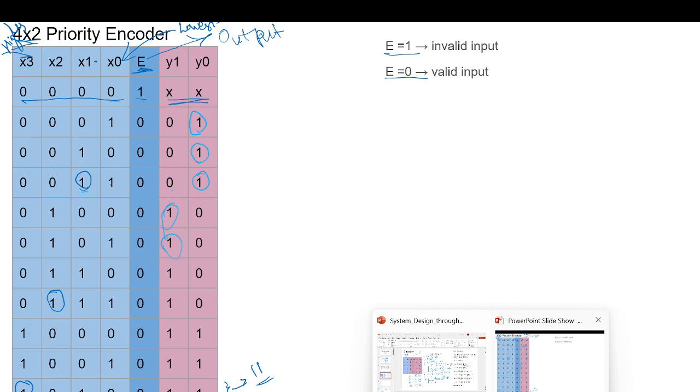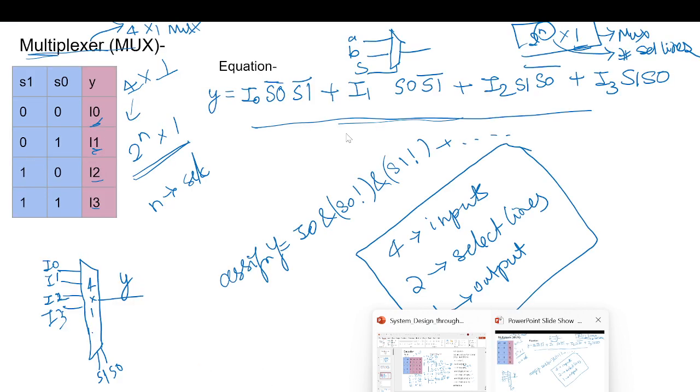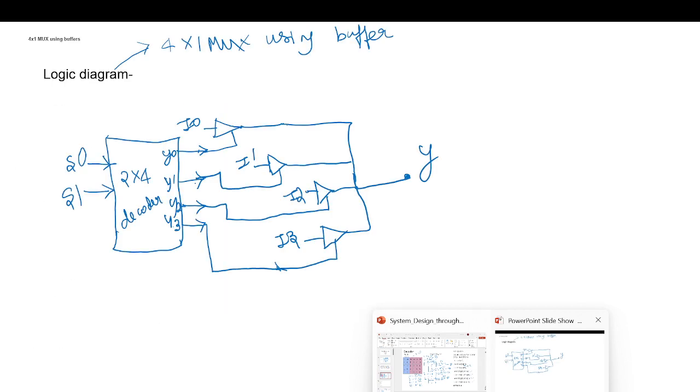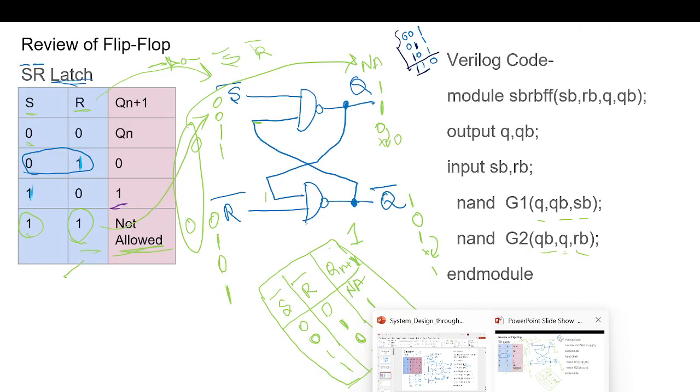Okay. What is the difference between the latch with enable and without enable? So a latch without enable is not a controlled signal. Whenever the input changes, you will find the output change. If I say I have 0, 0, then I can see a particular output. This may have some gate delay. Similarly, if I have 1, 0, I can see the output.